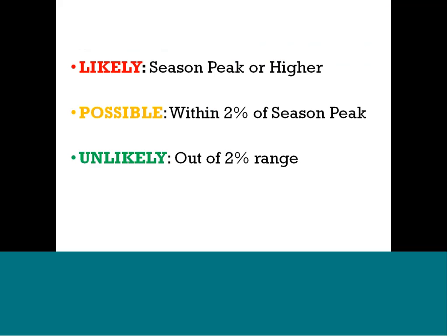If it's possible, we've found that ISO's predictions for each day can be a little bit off from what the actual ends up being. And so we found that if their estimate for the day is within 2% of what we think the likely threshold is, then we'll tell you it's possible. That's a day where you might really want to watch it, and you might proactively want to do some load shedding just to be cautious.